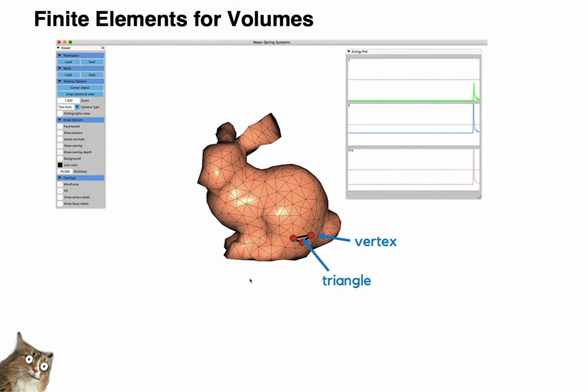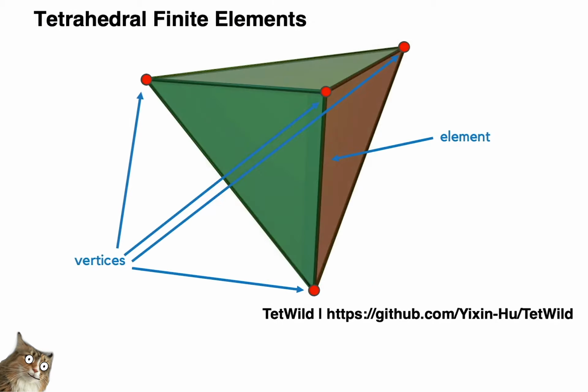To begin, let's remind ourselves how finite element methods worked when applied to volumetric objects. Recall that the initial step in the method was to divide the volume of our object into small subvolumes. And we chose tetrahedra to represent these subvolumes. From this choice arose one particular brand of finite element method.